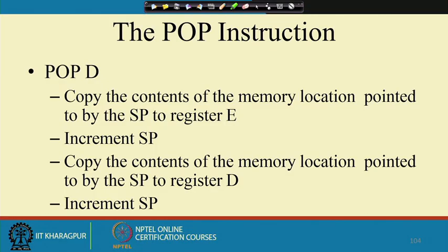Looking into the pop instruction. This is just the reverse of push. In the case of push, we are saving the content of a register pair onto the stack. The pop instruction is to retrieve the register pair value from the stack. Again, the pop works with a register pair, not with a single register.